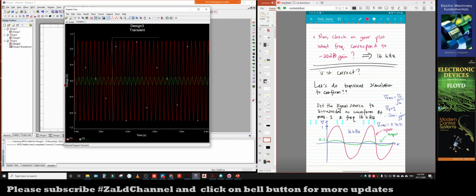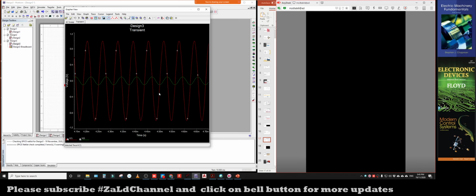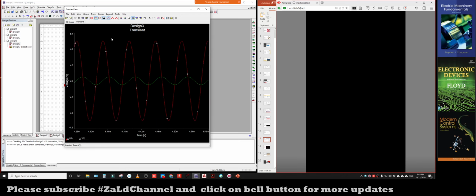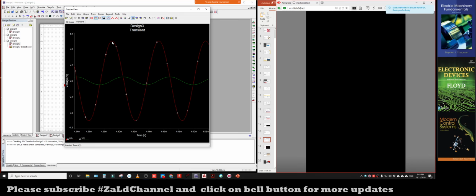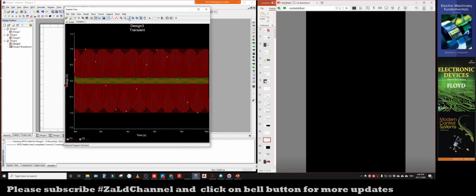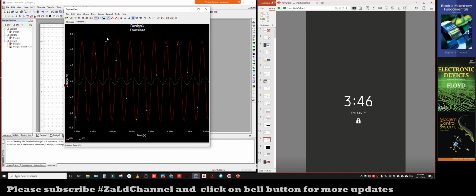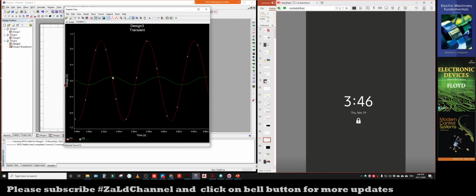As you can see, you can drag it like this to zoom in on your graph. All right, you can further zoom in. As you can see, the peak of the input signal here is about 1, about 1 volt. And then the peak of the output signal, the green one, is 0.1. If you drag this again, check this out. The peak of the green signal is actually 0.1.